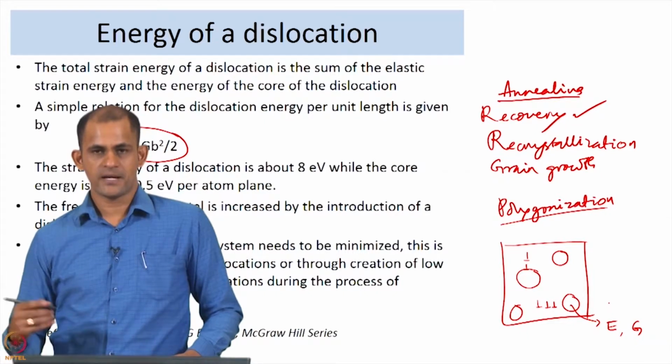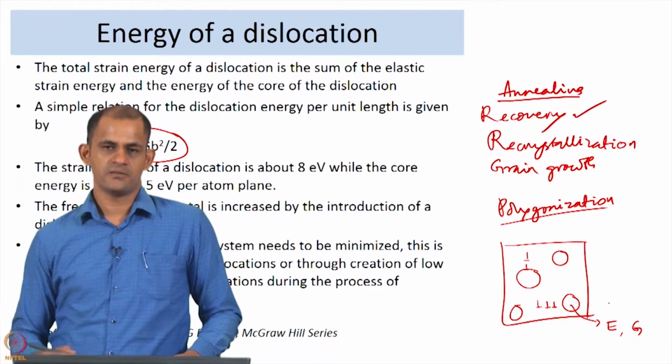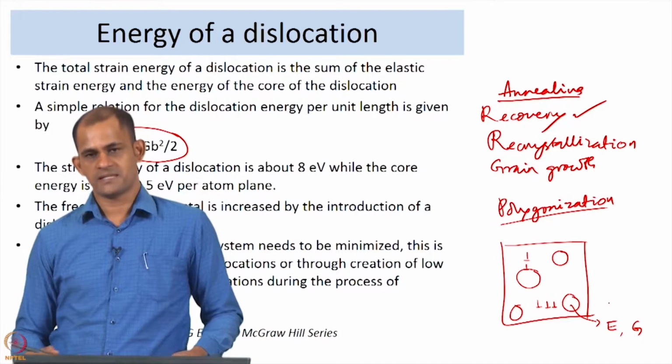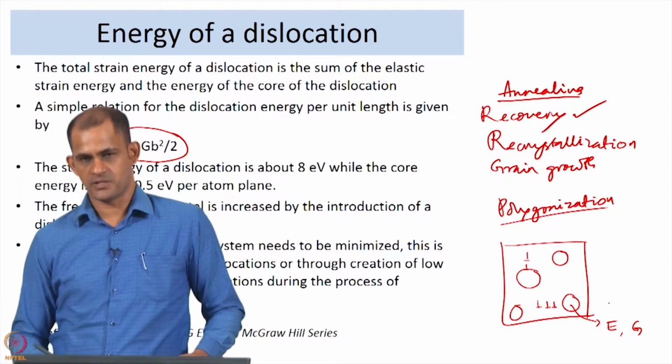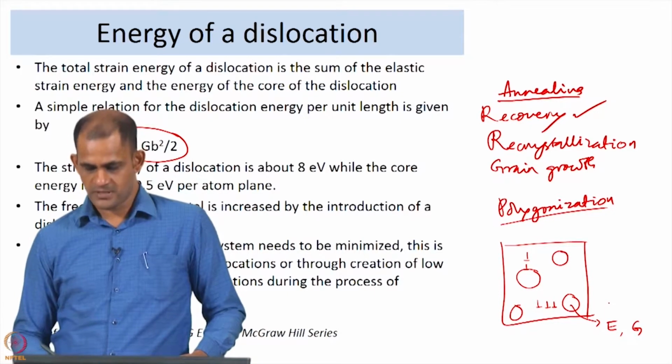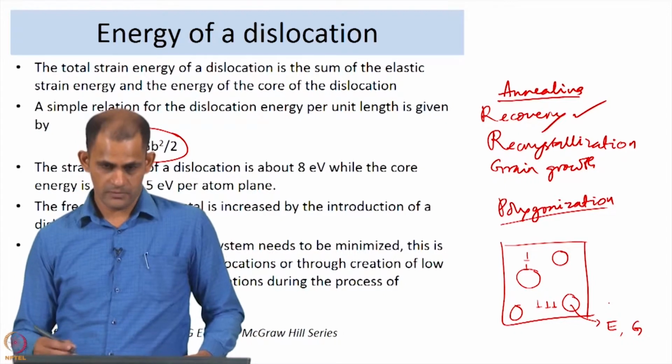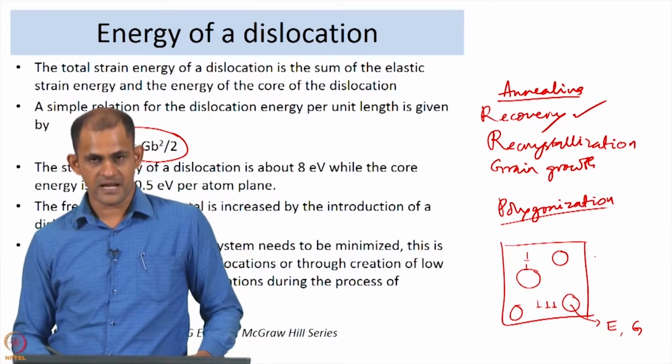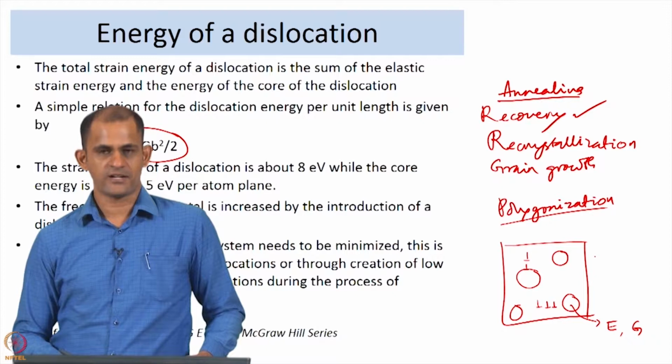That is because it is going to have a higher energy once it moves into a second phase with a higher elastic modulus. So, when you have second phases of that type, the material will have a higher strength.